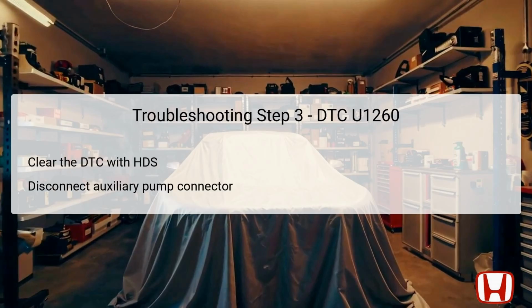For the third troubleshooting step, clear the current DTC using your HDS to reset the system. This will allow you to observe if the DTC reappears during further testing. After clearing the codes, switch off the vehicle to the off or lock mode. The next step involves disconnecting the auxiliary transmission fluid pump's 4P connector, which will temporarily isolate it from the system. Powering the vehicle back to on mode is essential, as this provides the necessary conditions for testing the circuit's integrity.